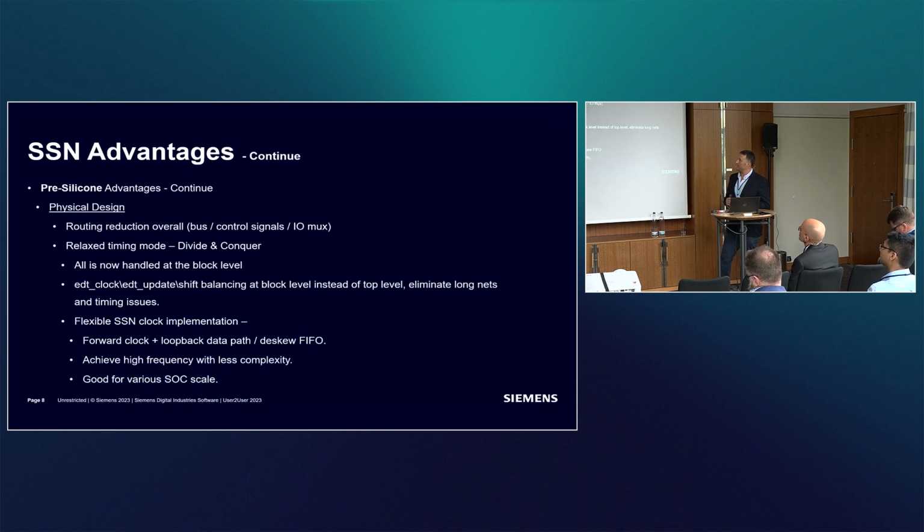Okay, on the physical design, I think they gained the most. It was a good experience for them also. It's much easier for the physical designers now when we have the routing reduction only for data and clock, and it's much easier than balancing scan enable throughout the chip and balancing the EDT clocks and the shift clocks. So now we are in divide and conquer mode, so everything is at the block level, and the controls, as I mentioned, are generated